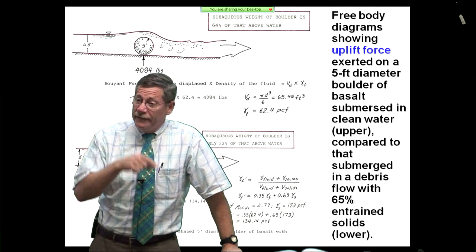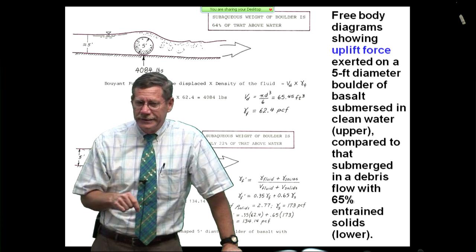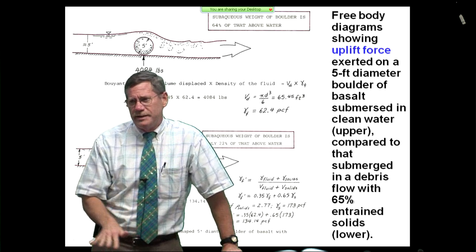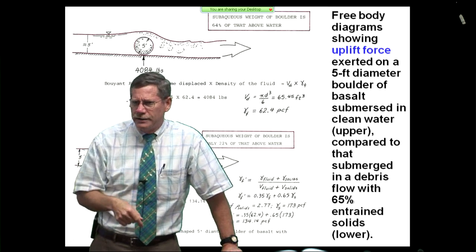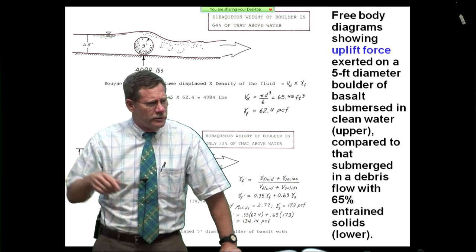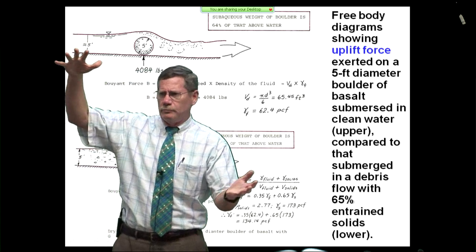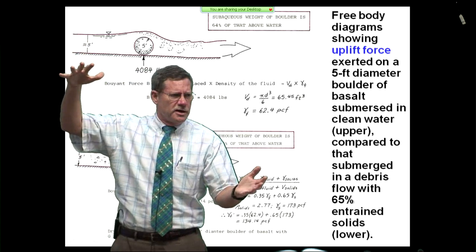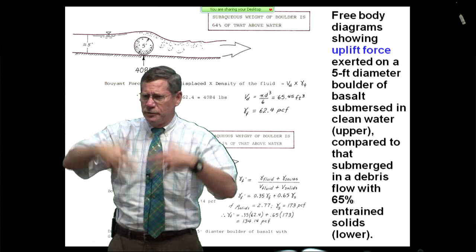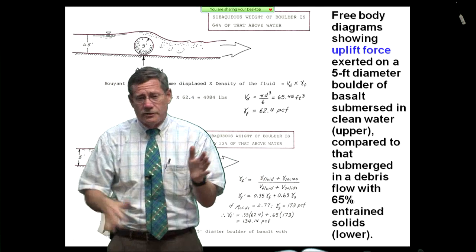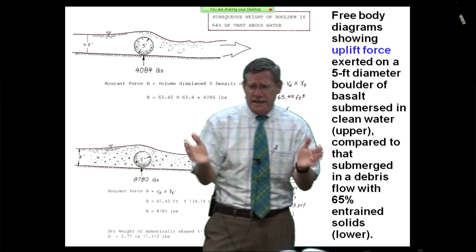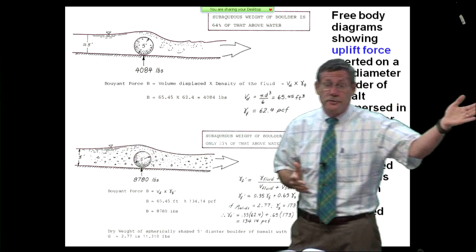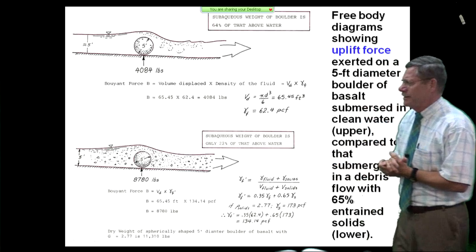Yeah. And then they got digging down deeper, and they had an inner gorge they had missed in their borings. They had hit and cored into bedrock. But the bedrock they cored into were 10, 20-foot blocks of basalt that had been brought down by debris flows in this inner gorge. They missed the inner gorge completely. In fact, that was one of the reasons they picked that site, because it was supposed to have less excavation than the site over in Boulder Canyon. Didn't turn out to be the case.